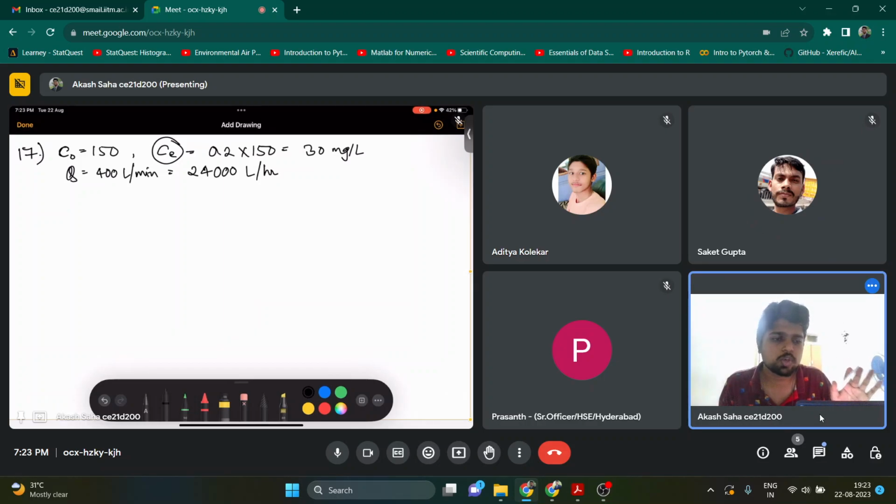So at the end of the three CSTRs that we have, it should give an 80% efficiency. My influent concentration was 150, and after 80% degradation, 20% will still be there, so I have multiplied 0.2 into 150. Did you get it? Okay, sir.